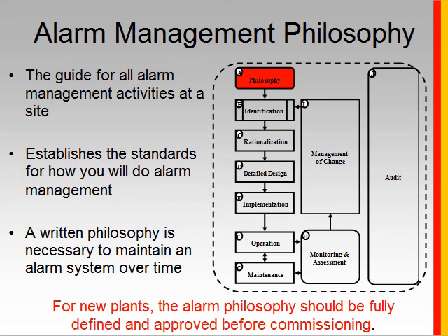It's really important that this philosophy is written down so that later on there's a lot of consistency that will be derived in the approach to alarm management. That all starts with the creation of this philosophy document, which is really the foundation of good alarm management. For new plants, it's recommended that the alarm philosophy document be fully defined and approved before commissioning begins.